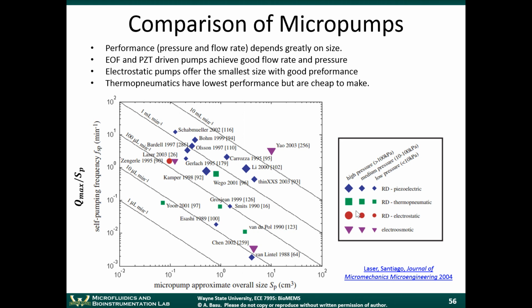Electrostatic pumps, you might think that because they have moving parts, they wouldn't operate as efficiently as electroosmotic or PZT-driven devices. But in fact, they do. And one of the advantages is that you can get decent performance because they can be actuated very rapidly.